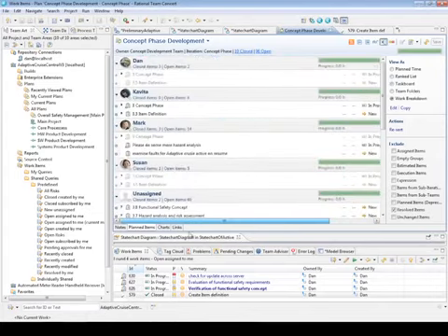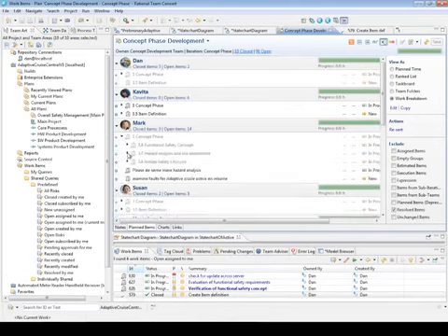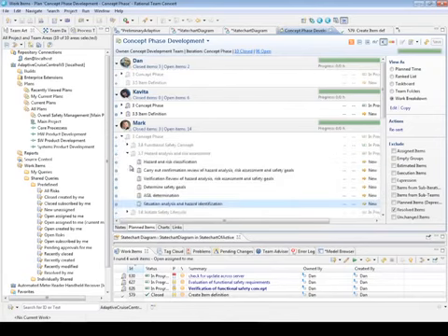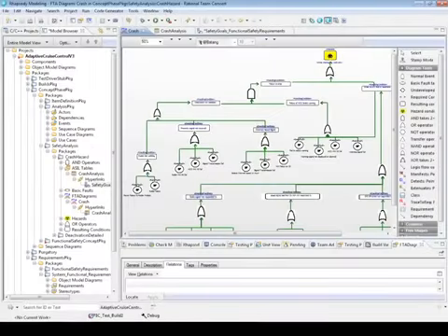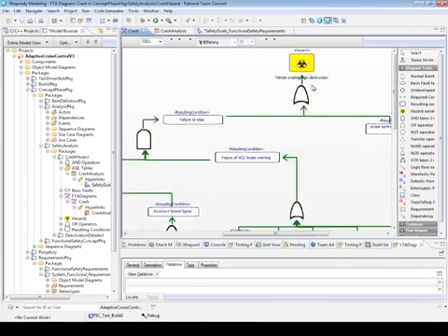Going back to the work breakdown, the next task is up to Mark, who will be doing a lot of work around the hazard and risk classification, or determining safety goals, ISO determination, then the situation analysis and hazard identification. Mark, using the safety analysis profile, can generate a fault tree analysis, of which this is an example, based around the main hazard at the vehicle level, which is a vehicle crashes into an obstruction.